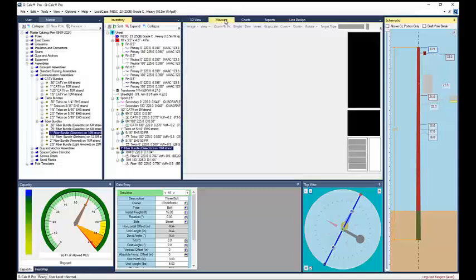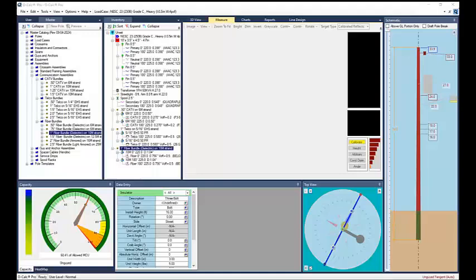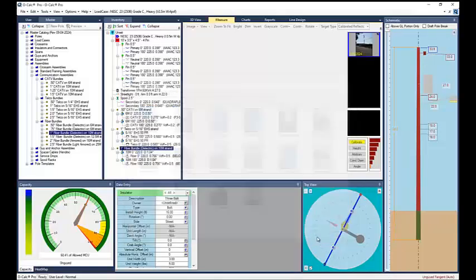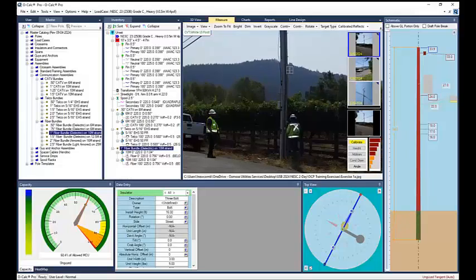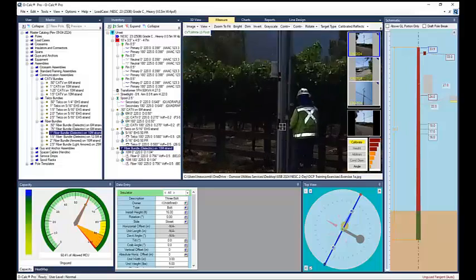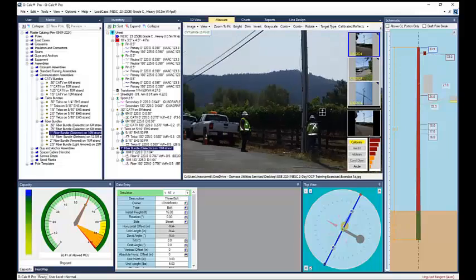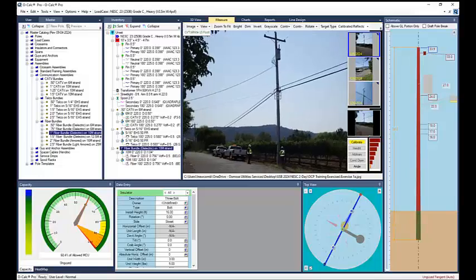Now additionally, in the measure tab, I could have brought some images over, and this is very common practice in O-Calc to bring in some images of the structure, calibrate that CVT, that white 13-foot telescoping fiberglass pole that we attach to the structure, step back and take a picture. Once these red reflective bands, these 4 points, are calibrated, then O-Calc is able to tell me the set depth of the pole from the image and the height of all the attachments.